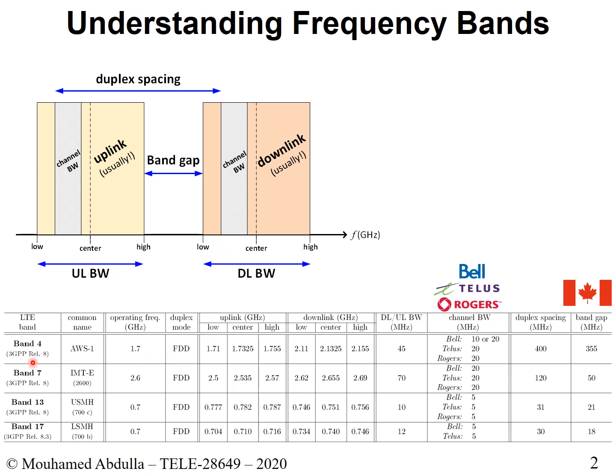Right? So if you look at band 7, these frequencies are larger than these frequencies. If you look at band 4, rather, this is what you observe. In band 7, the same thing. These frequencies are larger than these ones. Right? The downlink frequencies are larger than the uplink frequencies. In band 17, the same thing. These frequencies are larger than these frequencies. So the downlink always operates at a higher frequency as opposed to the uplink, which operates at lower frequency.